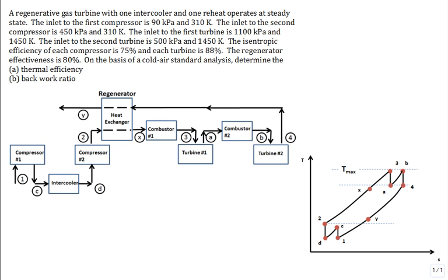All right, so last time we started this problem, and I want to finish it. This problem has a lot of states, and I follow the notation that's in the textbook. So we talk about states with numbers as well as letters: state C, state D, state X, state Y. And you can see that it has a compressor stage, then an intercooler, a compressor, a regenerator, a first combustor, the first turbine or high pressure turbine stages, then another combustor, then low pressure turbines, and then it goes through.